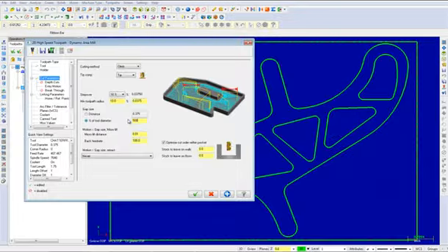I will now take a brief moment to explain a few of these parameters. Step over sets the distance between cutting passes in the X and Y axis. While using the HEM tools, the step over can be set up as 5%, 7%, or 10% of the tool diameter. Never eliminates retracts from the toolpath for these types of tool moves. And Optimize Cut Order defines the cut order Mastercam applies to different cutting passes in the toolpath. Once your parameters have been adjusted, select the Depth Cuts page.